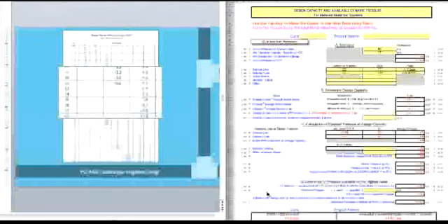I want to put a couple of pieces of information in here. Now, it's already done some of this. So line 14 here, it's actually already put information about the PSI loss per 100 feet based on what we entered up here on line 5. And so it's got a PSI loss per 100 feet for 25 feet of that type K copper, and it's already made the calculations. So these PSI losses per 100 feet are just coming from those same friction loss tables that we used previously.